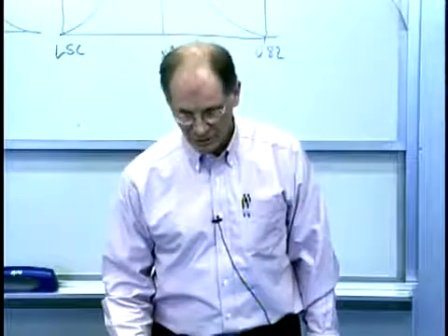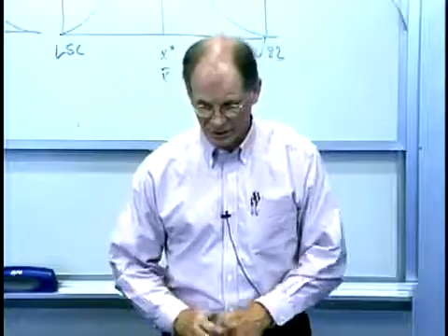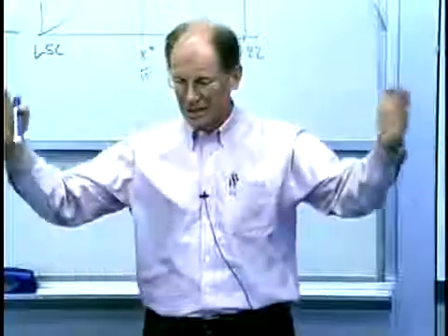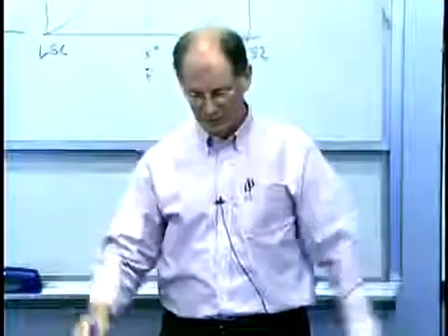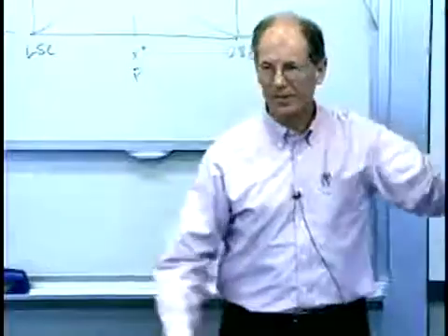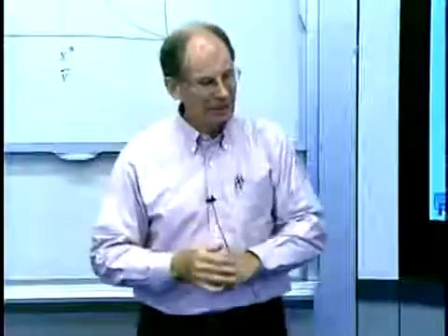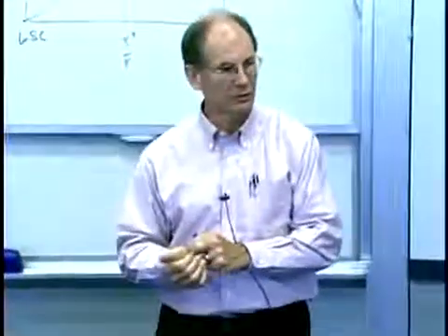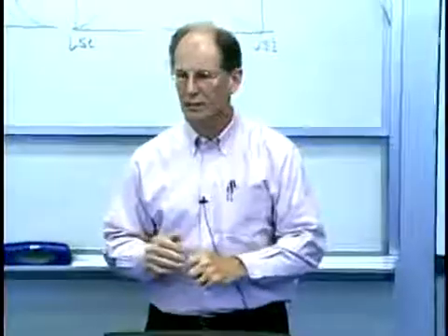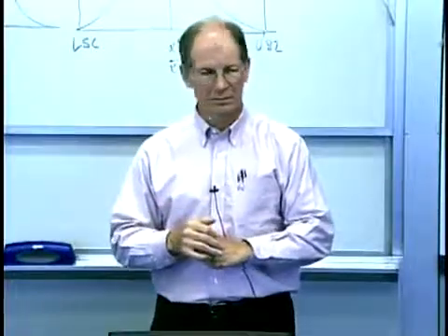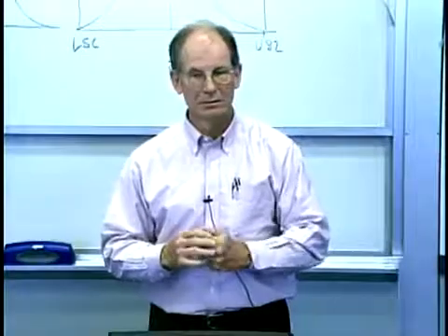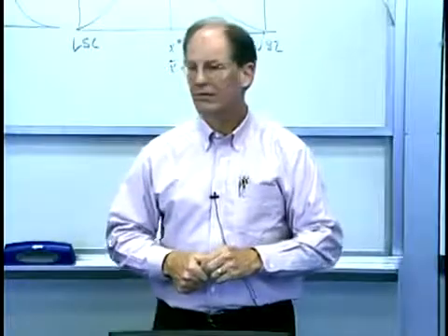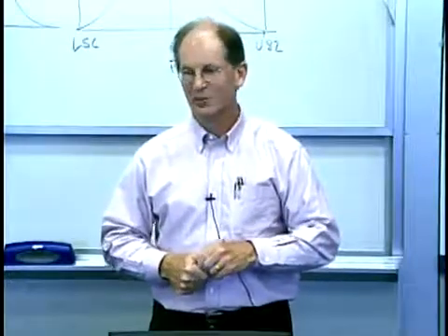Okay? So let me just end up with this and just say that there are a couple ways you can look at this. If I have a process perfectly centered and exactly plus or minus 3 sigma limits to my upper and lower specification limit, both CP and CPK will be 1. Okay, if that's the case, what's my parts per million, which many companies will use to measure their quality? What's my parts per million bad parts? Three out of 1,000. So it's a lot.